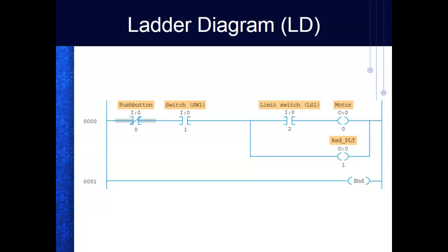This is ladder. So what we do is basically we'll have to learn some symbols, but there are very few symbols. There are a lot fewer symbols in PLC ladder than there are in relay ladder. Unfortunately, when you connect the inputs up to it, you're supposed to use the symbols that you use in PLCs. And we'll be doing that a lot this semester. So we'll start off with them giving you a PLC program, and then you'll develop the relay logic program from that.